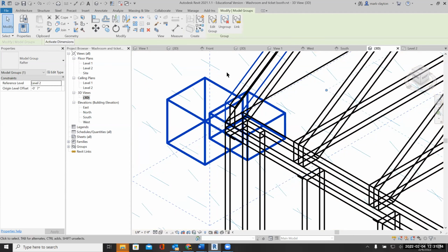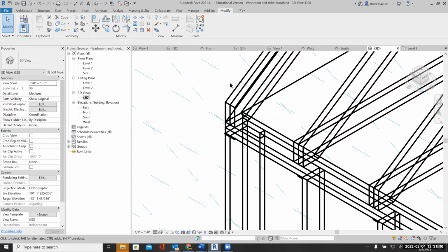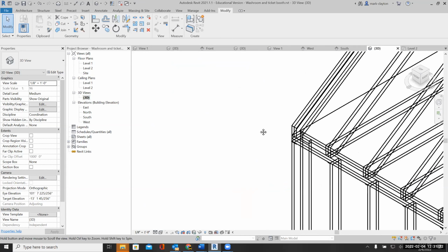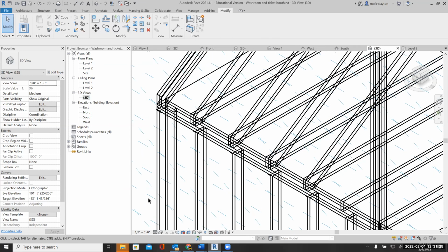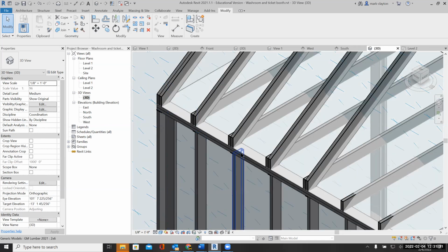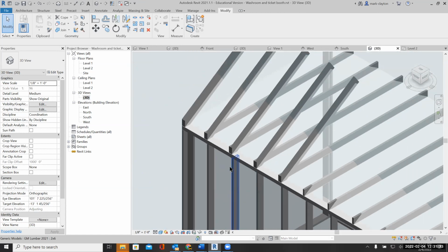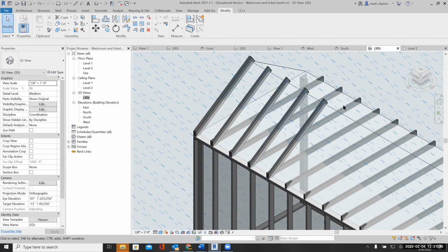And the interesting thing is that when I cut them away in that first group, it cuts them away in all of the copies of the group. So I've made all those rafters the way they need to be. And I'll go and look at its shaded view, and it looks pretty much right. Looks good. So that's how we would do the rafters.